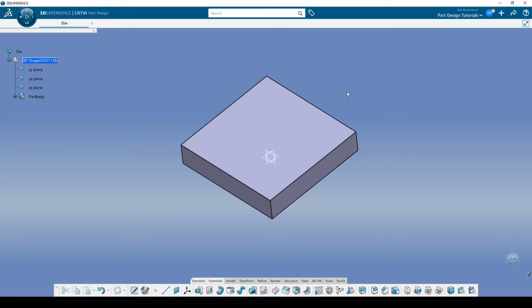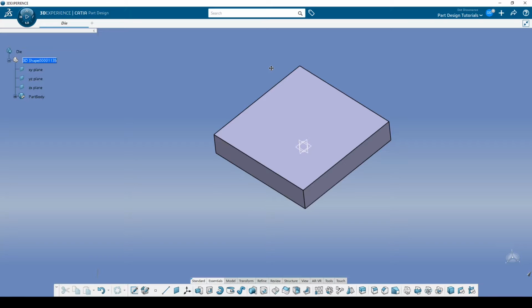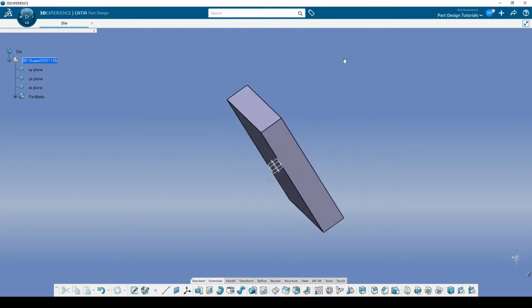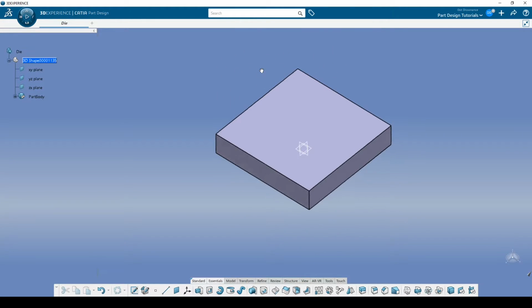And you should be able to press it. I have run across a few mice out there where the middle scroll wheel doesn't actually press like a button, which was kind of shocking to me because I thought that would be default. At any rate, the middle mouse button, if you hold it in, you're going to get pan. So that's pan like this. And then if you hold down the middle button, number 2, and hold down button number 3, then you're going to rotate. So that's the middle and the right mouse, and then it rotates around, okay?